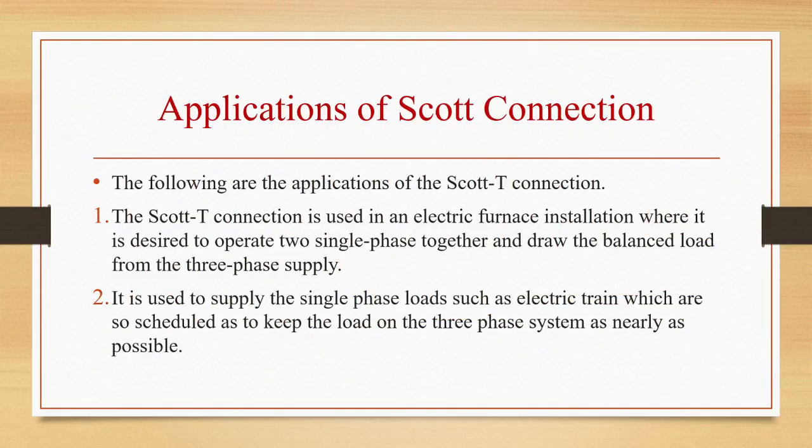Let us see now applications of Scott connection. Following are the applications of the Scott-T connection. First one is Scott-T connection is used in electric furnace installation where it is desired to operate two single phase transformers together and draw the balanced load from the three-phase supply.